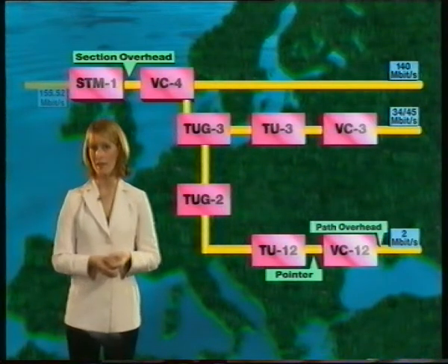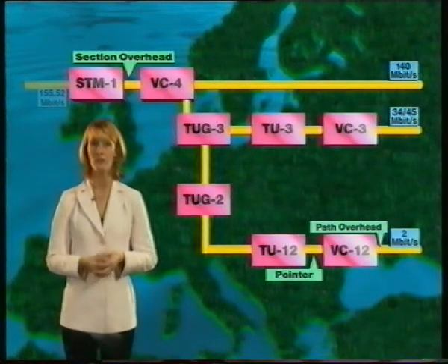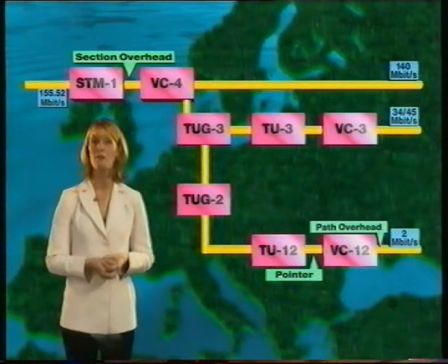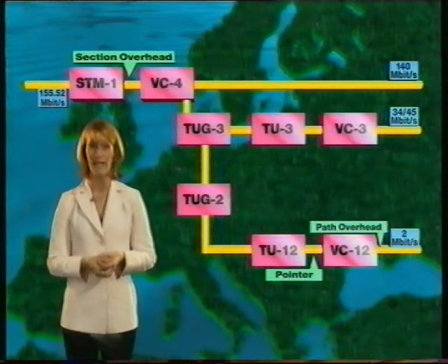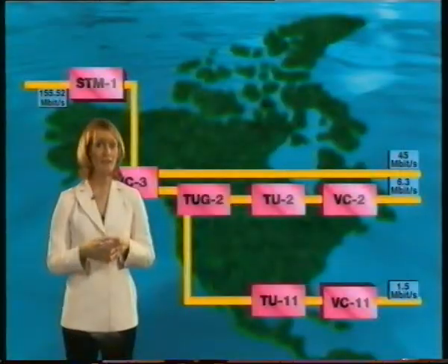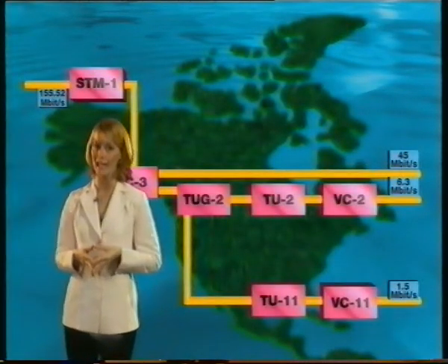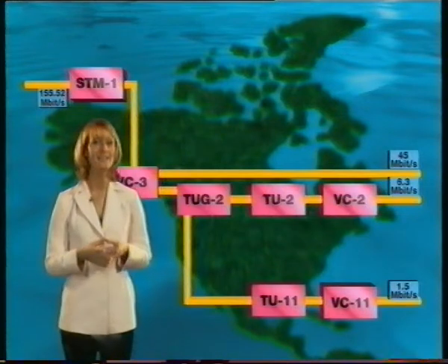STM1 is a fundamental building block within the synchronous digital hierarchy and has a transmission rate of 155.52 megabits per second. Earlier I said that one of the advantages of SDH is that it conforms to internationally agreed standards. This graphic shows the hierarchy as implemented by the American National Standards Institute, or ANSI.